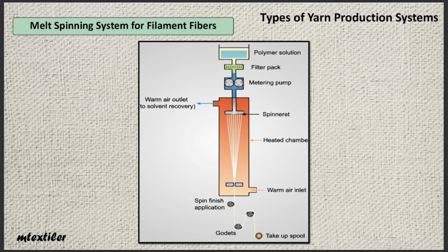After complete homogenization of the polymer solution, it exits through the spinneret, which is a metal component with numerous holes, each hole corresponding to a single filament fiber. The shape of these holes can be circular, triangular, etc., depending on the cross-section we want from the spinneret. The filaments exiting the spinneret are controlled by the airflow and rollers in the machine, quickly cooled and solidified.